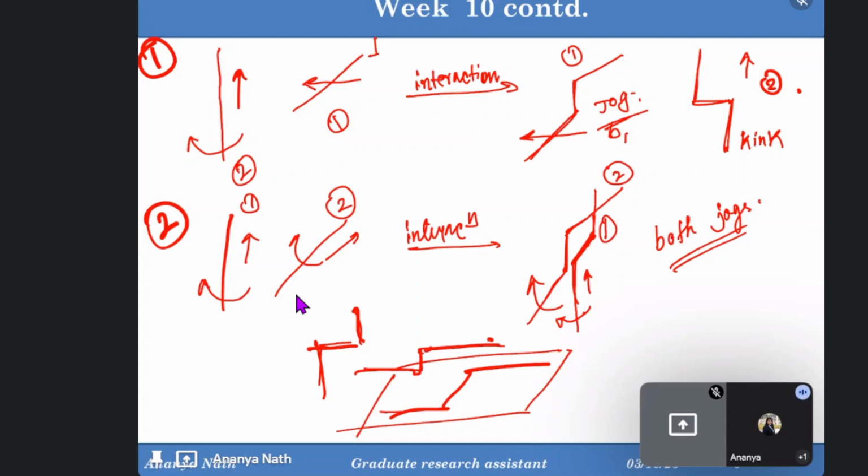You are not aware of the condition of plane 2, whether other dislocations are also present there or not. So whenever it's changing its plane, it will be more difficult for the dislocation to move. If it's in the same plane, it can still move, because we know there was only one dislocation present in that plane. Is that what you are asking?